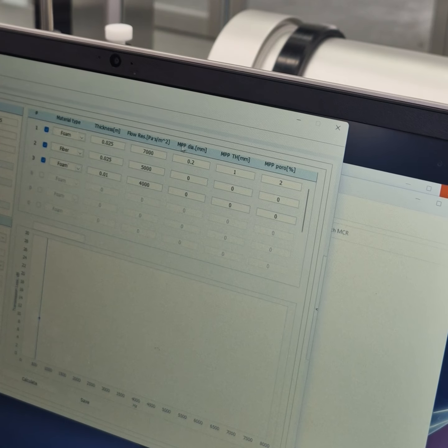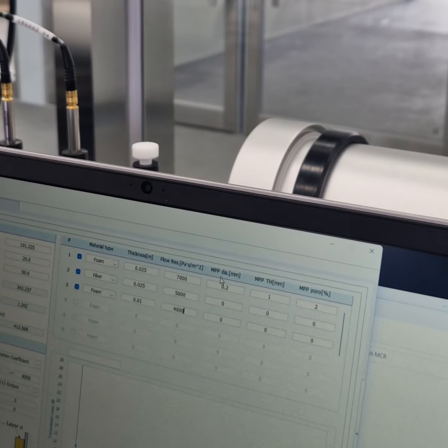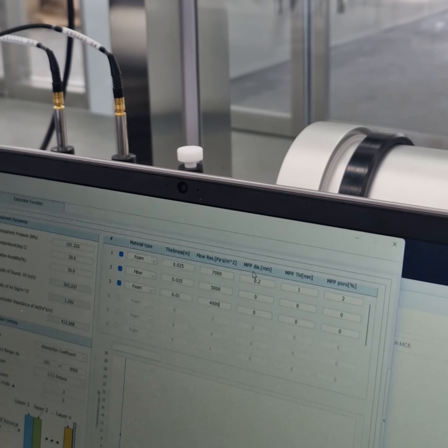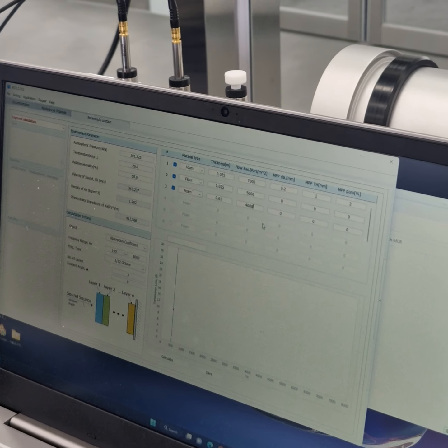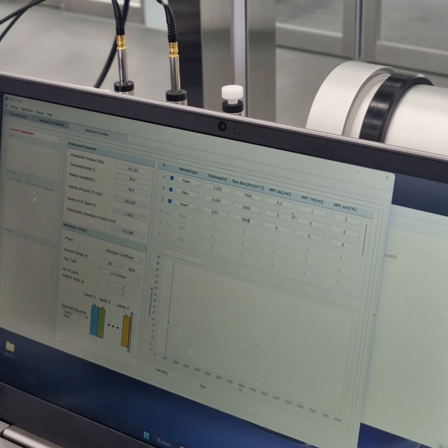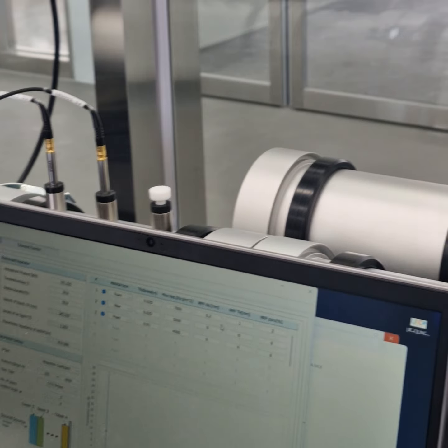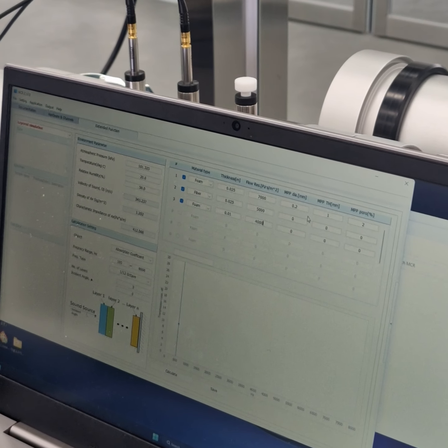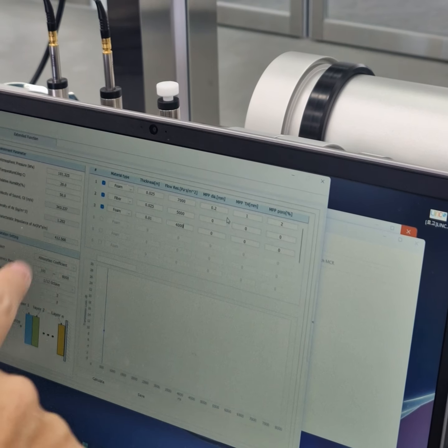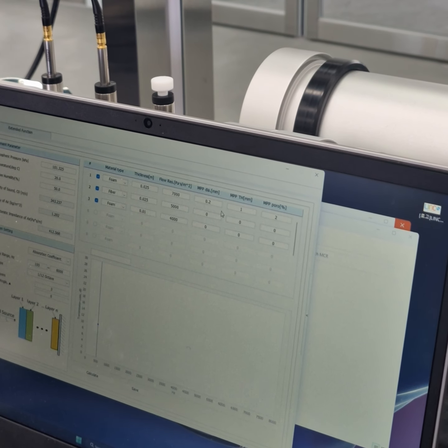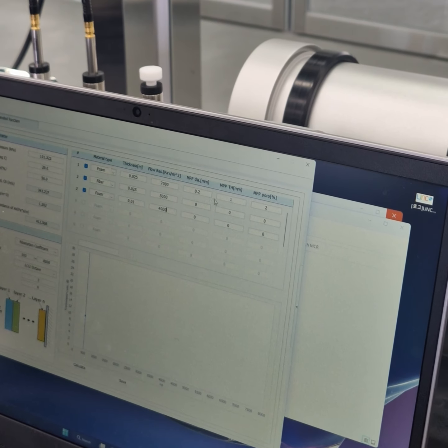Okay, and then I don't think you need this. This doesn't matter because MPP means micro perforate panel. Yeah, this has way more things. If you encounter this, you can contact me. But this is also another type of material. It's like a metal plate with very tiny micro holes on it, which has good absorption at low frequency. So this little software can also predict that part. But if we are trying to use foam, fiber, foam, then we don't need to do anything on this.